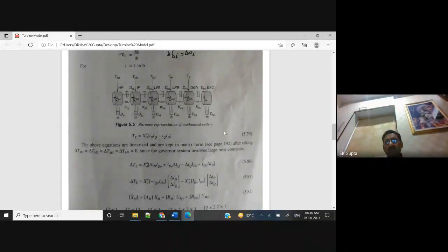So all the ABC currents, all the phase currents of the stator, if you refer them on the stator frame of reference into the DQ axis, in the DQ axis, D and Q are the rotatory frame of reference and ABC are the three phases. So on the stator side, in the rotatory frame of reference, the current is represented by ID and IQ, and this is the maximum short circuit current flowing into the stator when.